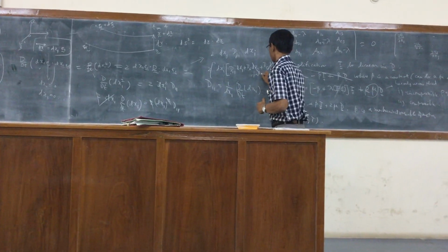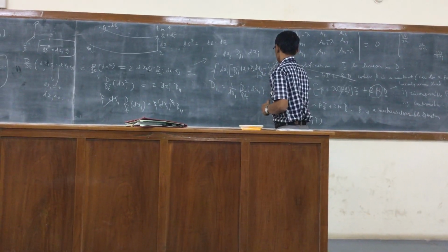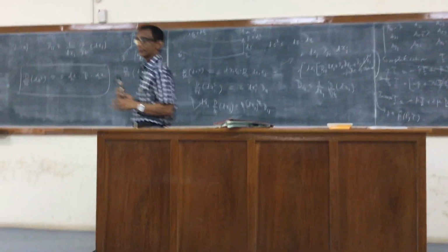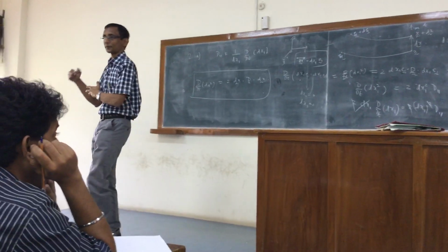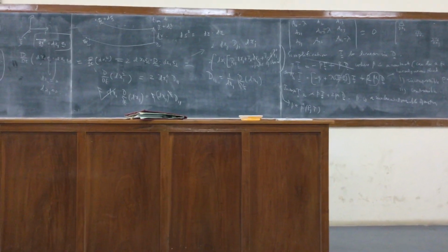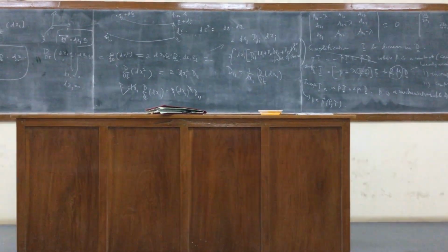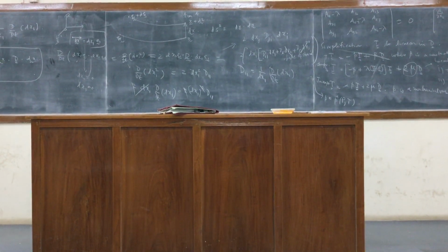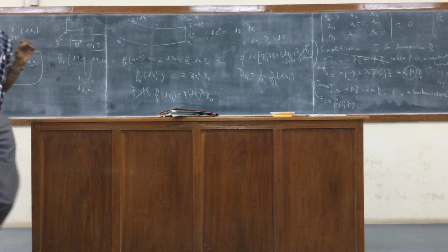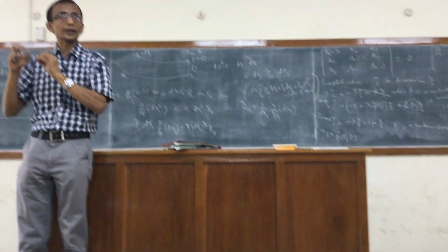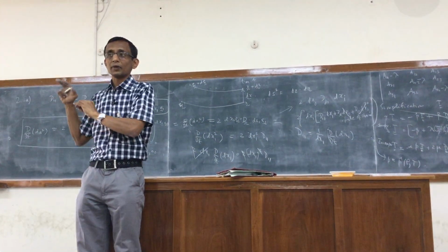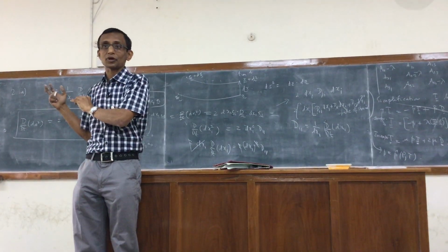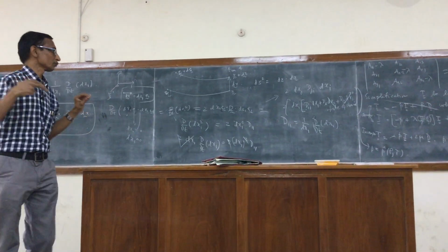It may be regarded as a rate of strain, change in length, in elasticity. Often it's a strain; you've heard of the stress-strain relation. Of course, Hooke's law is the simplest case, the one-dimensional case. You have to consider more generally the three-dimensional case. Typical constitutive relations in elasticity relate the stress to the strain, whereas in fluid mechanics, the stress is related to the rate of strain. This is one way of interpreting it.